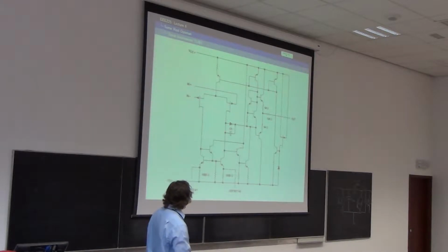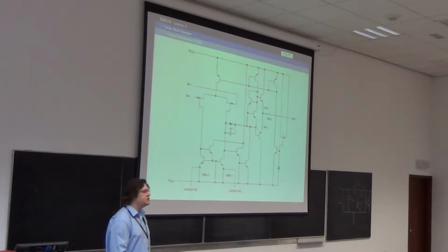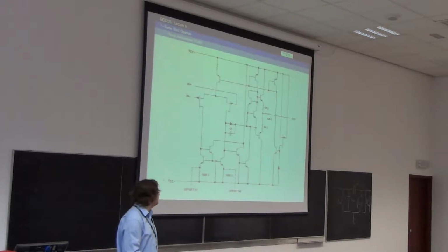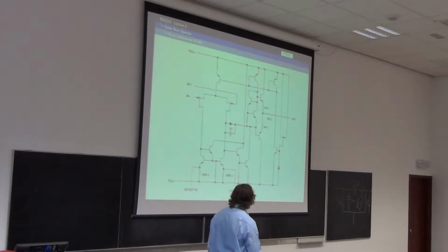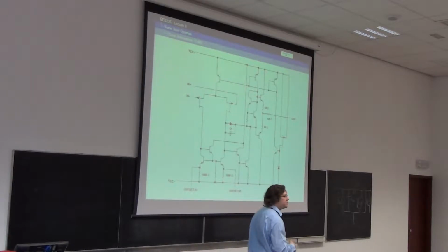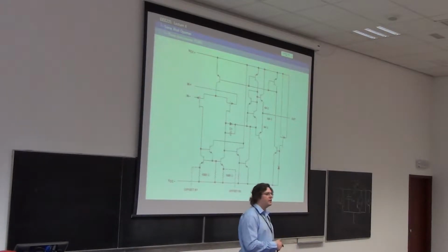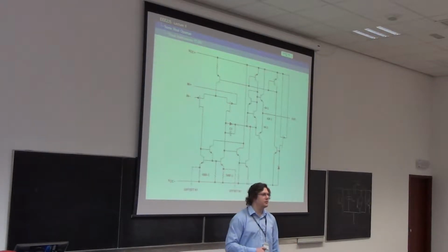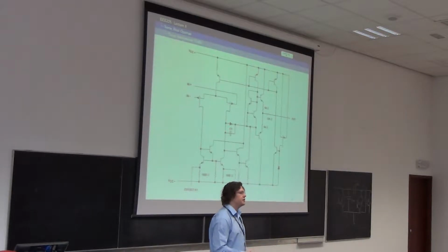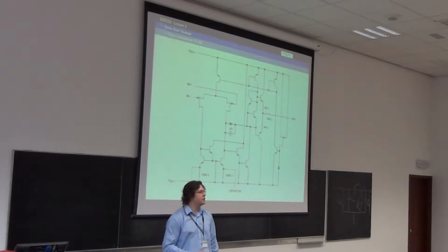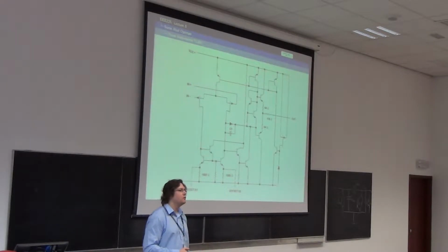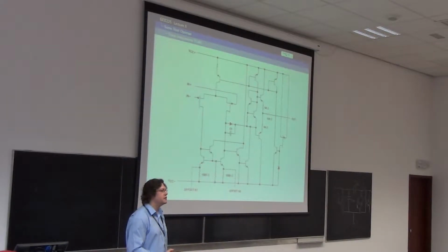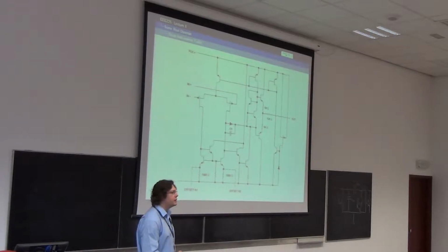The reason is you can set up a current which is known from a particular JFET by connecting its gate to its source, and you'll get the IS for that particular JFET. And if you know the dimensions of that JFET, because you made the mask that made the JFET, you'll know what that IS is going to be. IS for a JFET is not small, like IS for a bipolar transistor. It's a value usually in milliamps.